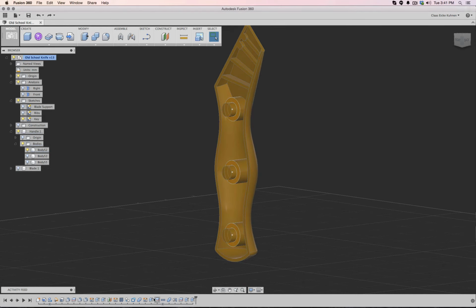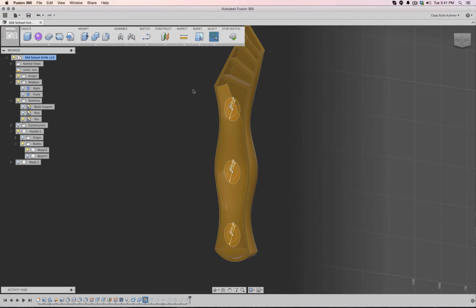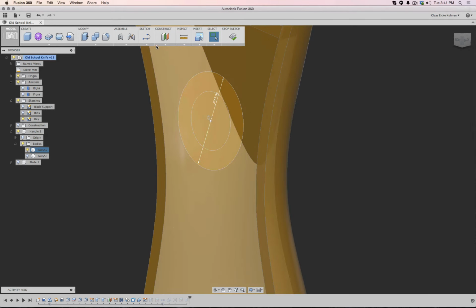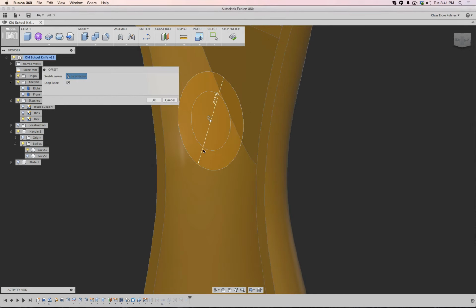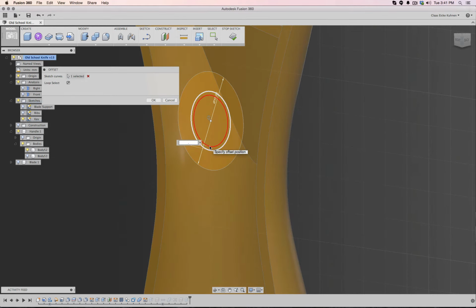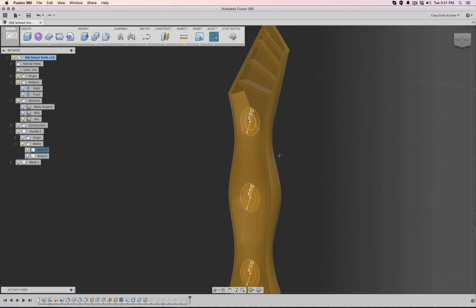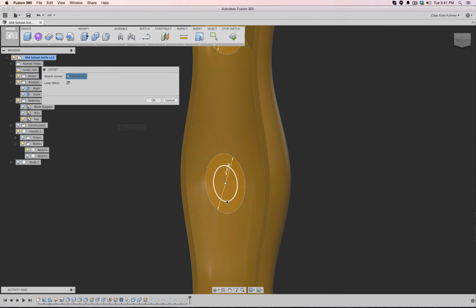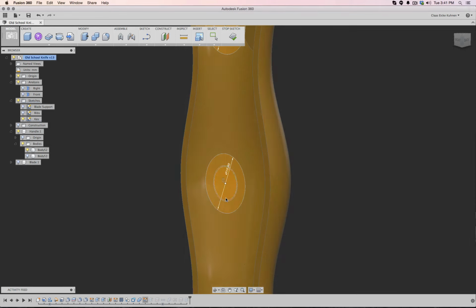I could actually also go back to the original sketch. So for example, this extrude I delete, go to this sketch, edit, and then do another offset. This one, just 0.1, maybe, oh, I'm sorry, 1 millimeter. No, I don't know, 0.25. The MakerBot can't be so imprecise. I don't really know the tolerance of the printer right now, so I have to guess, to be honest. 0.25.